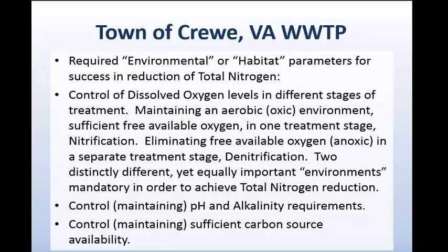Controlling and maintaining sufficient carbon source or a food source. In the denitrification process, you have to have sufficient carbon source to complete that process. On the opposite end of the spectrum, in order to accomplish the nitrification stage, you actually have to limit carbon source concentration. But whether we're talking about nitrification or denitrification, paramount to removal, we have to have available in the select environment the item or the constituent that we're seeking to remove.